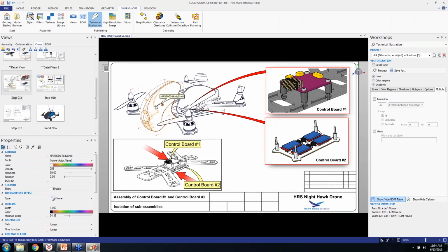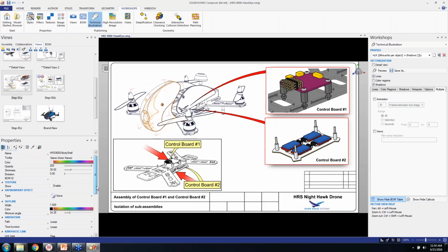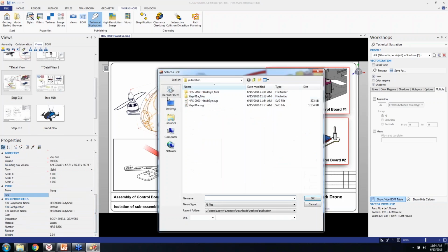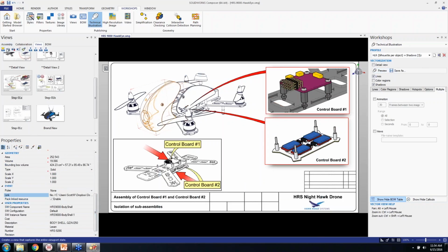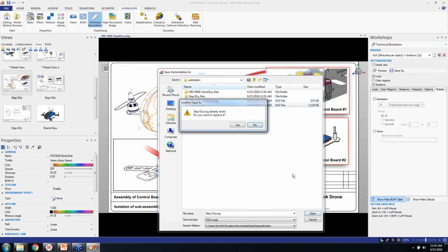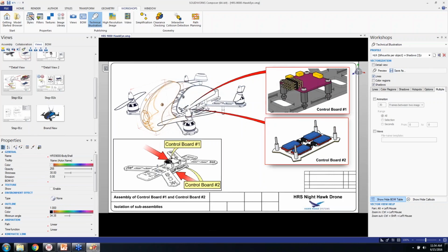And it's more of an interactive parts list, part manual, online experience kind of thing. And so I'll say whenever I click on that, it's going to do something. So now I can go to link. I can link this to the second SVG file. And let's go and update this, and I'm going to save it out and overwrite that guy. It'll make sense here in a second why I just did that.